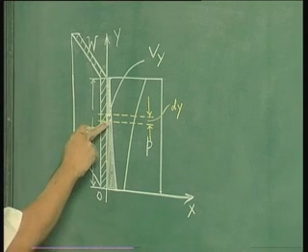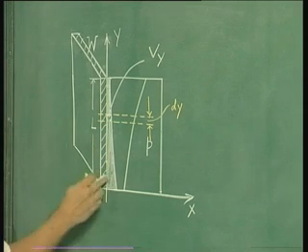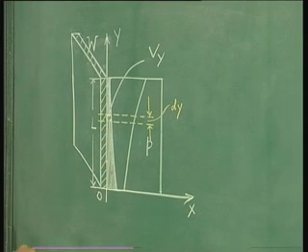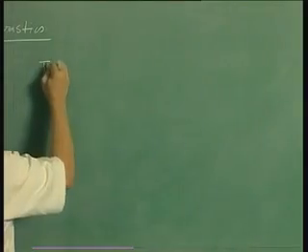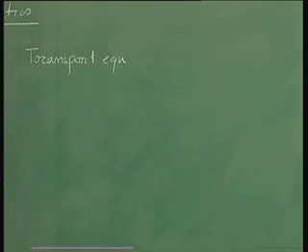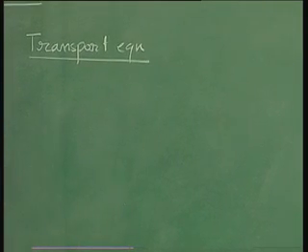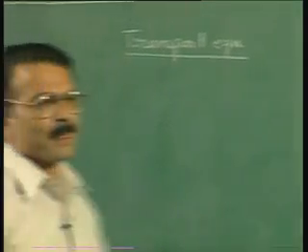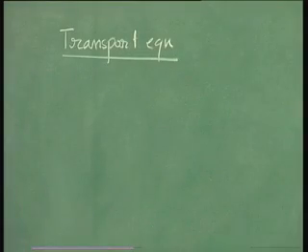So for example, if you take the transport equations, we neglect the equation for holes because in an n channel device the inversion layer is because of electrons and the hole concentration in this inversion layer is really very small. Therefore, as far as the transport equation is concerned, we are concerned only with the electron transport. So one of the equations drops out. Now further, in the equation for electron transport you have 2 terms, that is the current because of diffusion and the current because of drift.